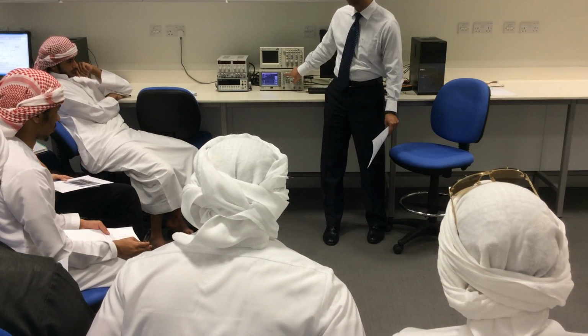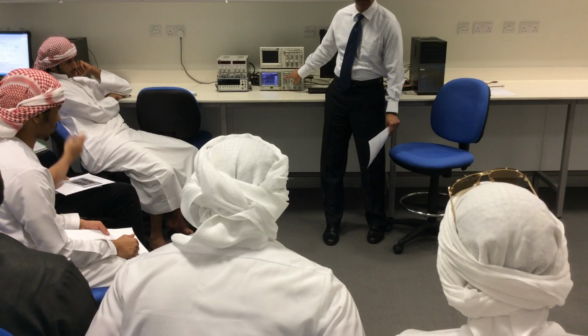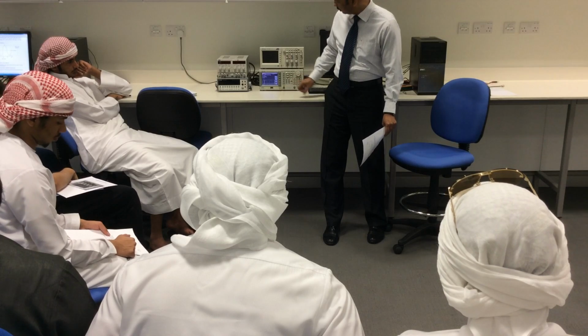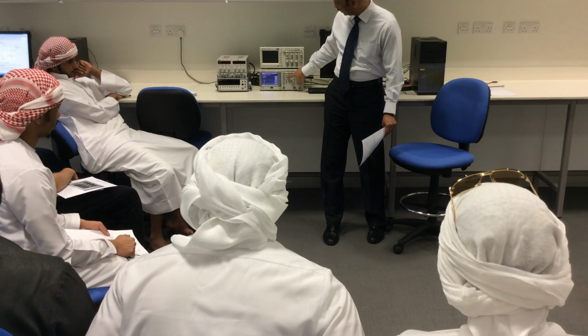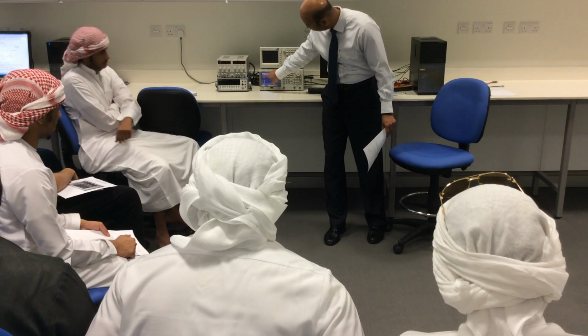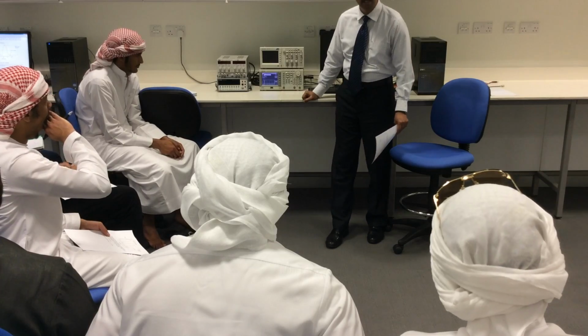So this is sine. I'll keep it like this. If you want a square, you will press this, and for triangular, you will press this. Just for today, we'll keep it like this. And what are the things you need to provide here? Frequency. So you press this frequency. You see this frequency here? It is highlighted. Now you will enter a value.